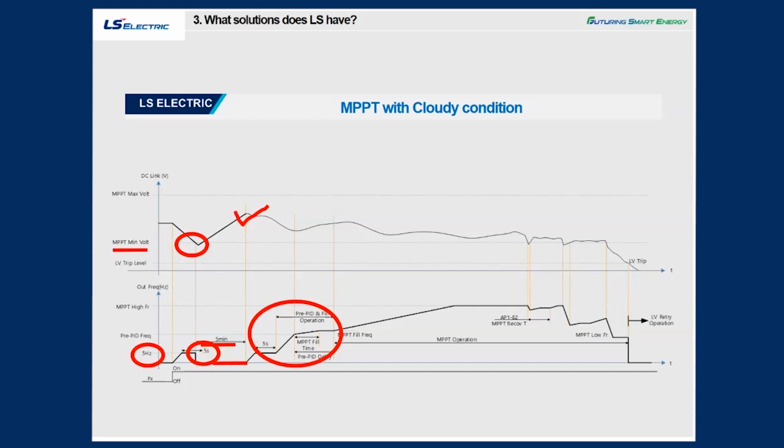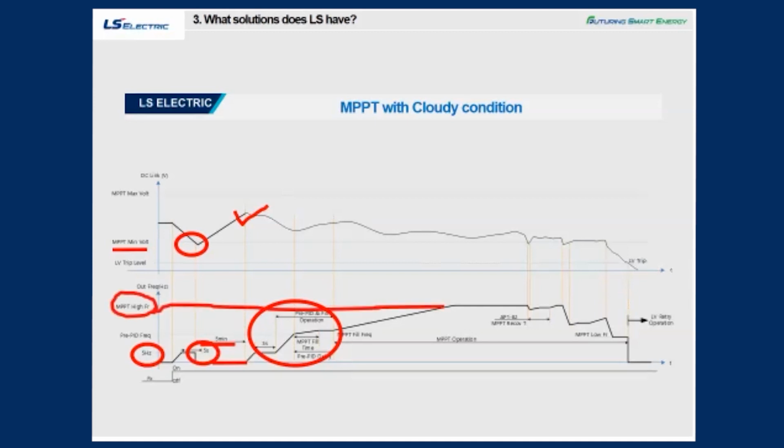Depending on the type of pump, vertical or horizontal, MPPT field will be executed. For a submersible pump, when a certain pressure of the pump is secured, the frequency of the pump must be increased gradually afterward to prevent a sudden change in the pressure of the pump. After MPPT field, the alpha frequency increases to the MPPT high frequency over the MPPT acceleration time.